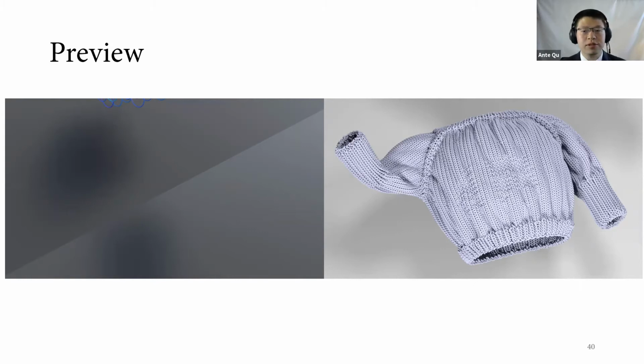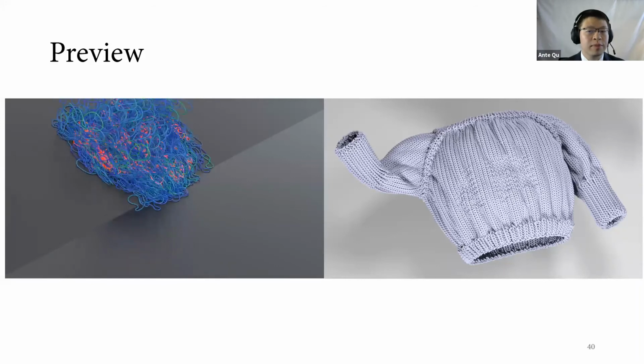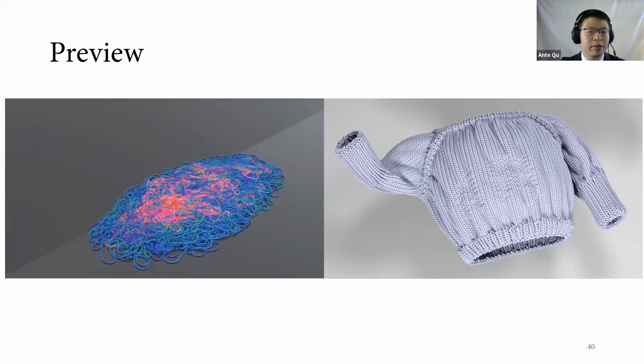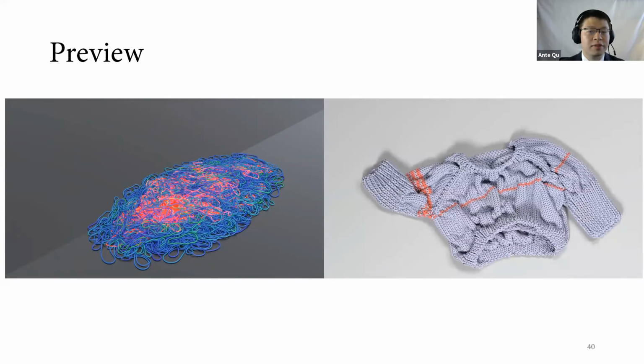In these examples, we compute a checksum during various stages of a simulation and detect changes in the topology. On the left, as the rubber bands slide in the simulation, we highlight in red the rubber bands that illegally link with other rubber bands. And on the right, we highlight rows of a yarn level cloth model that pull through each other during a simulation.